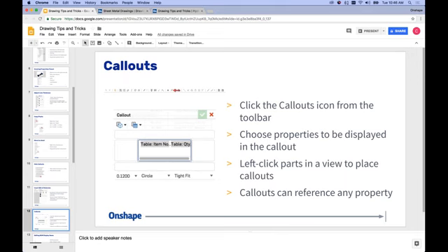Question: if you delete item 6 on revision A, will the item numbers greater than 6 remain static with a revision change, i.e. item 10 is the same item in both revisions? I believe I understand this. So just to restate it, if you delete item 6 in the bill of materials, I'm assuming on revision A, will item numbers greater than 6 remain static with the revision change? In other words, there's a blank space at 6. I suspect what would happen today is it would reorder and shift up. It would not remain static after I delete.